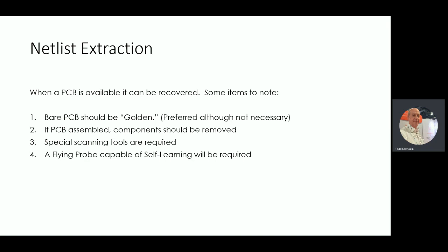So we put that on there, and we tell the machine to self-learn, and it goes out and learns that board by taking the probes out and interrogating each of the pads to make a netlist. And when that is created, we actually have a netlist on the machine. Now, this isn't necessarily in a form right now where you can go build the board, but it does have the intelligence.